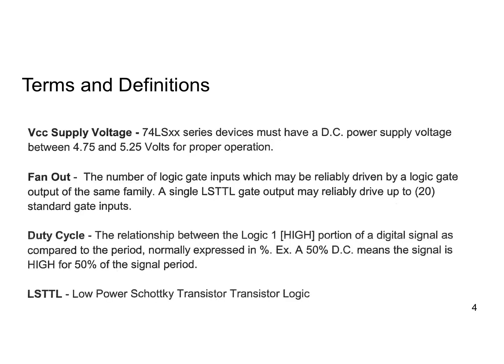Continuing here, VCC, the supply voltage. Again, this is from the data sheet. The manufacturer states that the user must guarantee that the DC supply voltage, which must be filtered and regulated, cannot be less than 4.75 and shall not exceed 5.25. So that's your job, if you're designing the circuit, to make sure that the power supply voltage always falls within that range.